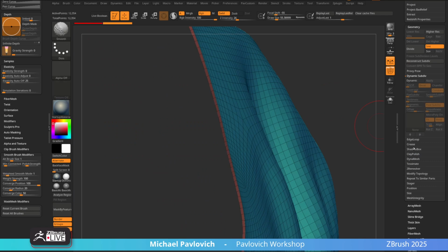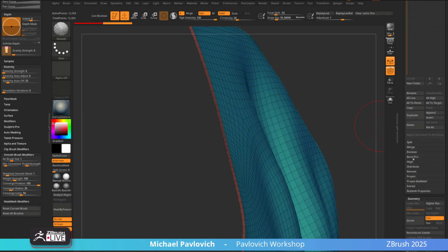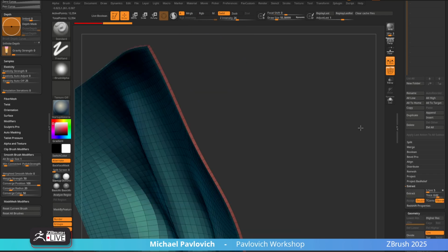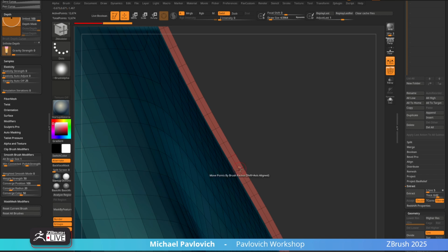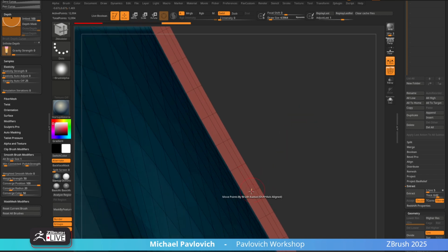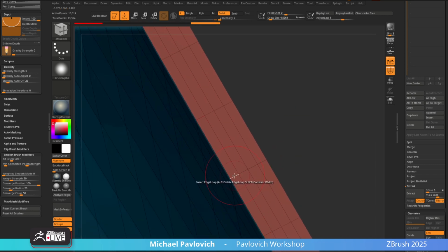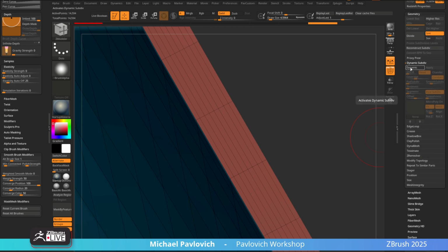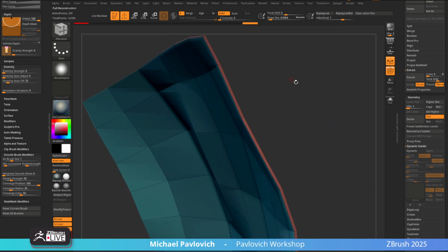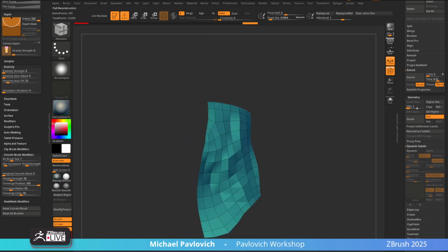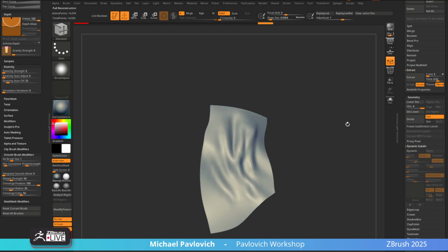Geez, we're getting all of them today, everybody. Subtool, Extract, turn off smoothness, crank up thickness, apply it. You'll be in the exact same position. Then you can just go in here and say, insert, one down the middle, that's one reconstruct. One down each side of that, that's another reconstruct. One down each side of these, that's another reconstruct. And then now we can go through here and say, Geometry, boop, boop, boop. There we go. So now we have our cloth, plane, subdivision, etc. If that makes sense.